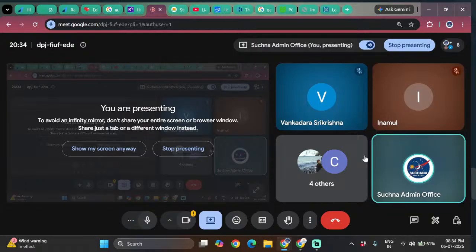And this is about today's session, where we discussed the different rules that we should follow if you are using gold fingers, like a 45-degree chamfer. We can use 30 degree or 20, and 20 is also allowed, but it's better to avoid because it takes so much space. 20 degrees is usually not acceptable. According to the specification it can be used, but it's better to avoid as much as possible. You can go with 30 degree as an intermediate value, or else the standard one, the 45-degree chamfer.